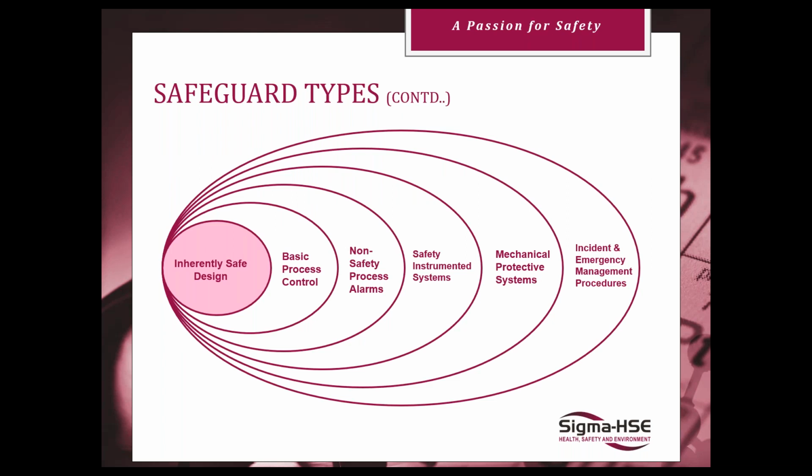All right. So most people are usually familiar with the safety onion. The closer to the center, the more effective it is, starting with an inherently safe design. For this, the safest plant is a plant where, it's designed to operate so you can't overfill it, you can't overpressurize it. Not always common, can be expensive. That's why we go to, all right, basic process controls are your next step. That's how you keep your process within its desired set points. You control flows, levels, temperatures.